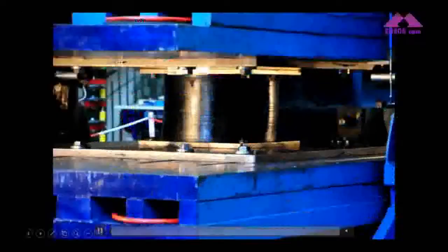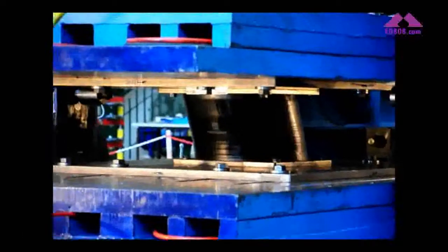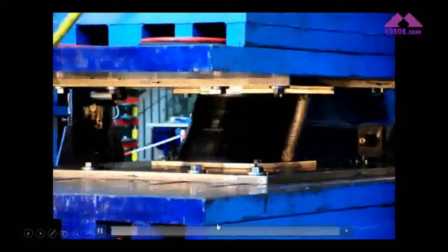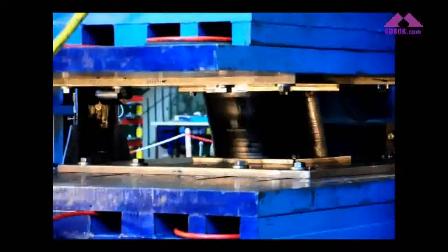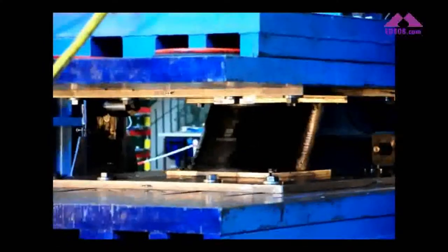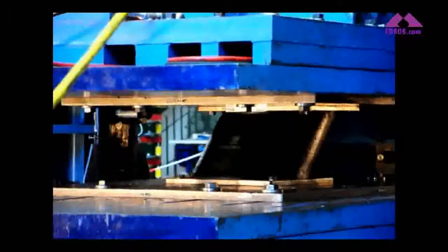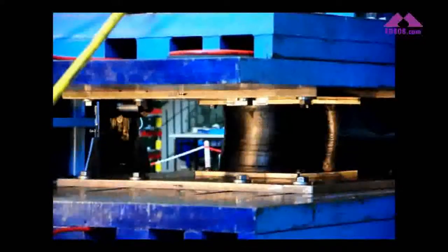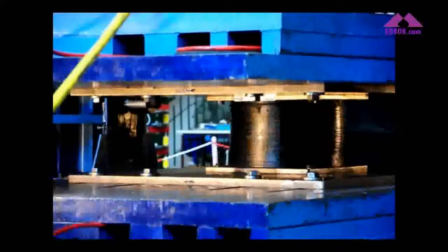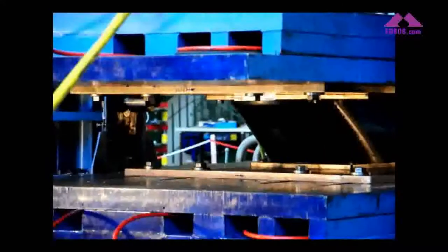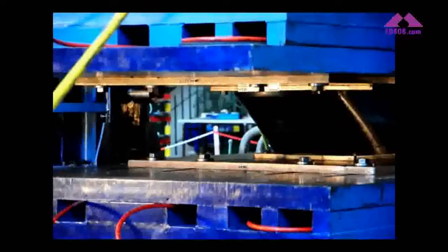Let's see a video from a test. It's a rubber isolator test, which was done in Italy at the EU Centre. There is something like a shake table that is moved. There are 3 cycles. You pull 3 cycles up to a displacement, and you increase the displacement and repeat the test. And on top of it there is axial load pressure, and as far as I remember, for this case, the maximum axial load was around 10,000 kilonewtons, which is 1,000 tons.